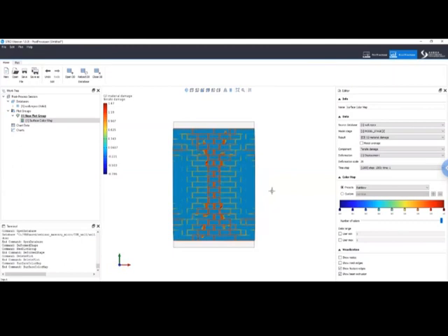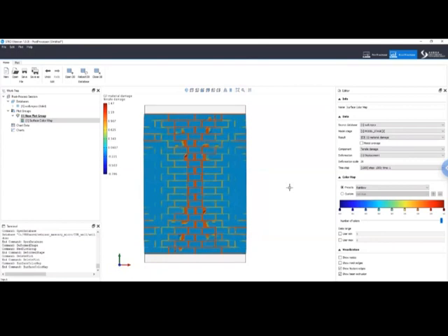Now some note about the damage. The damage variable, actually the damage results is made of 2 components, the tensile damage and the compressive damage. Now, typically what you want to see is the tensile damage. Anyway, the damage variable is a variable that goes from 0 to 1. 0 means the material is still elastic. 1 means the material has lost completely the load-bearing capacity.